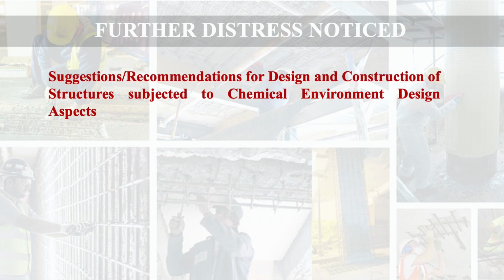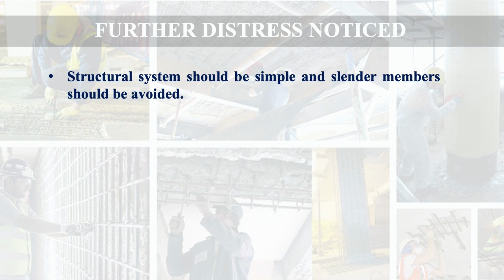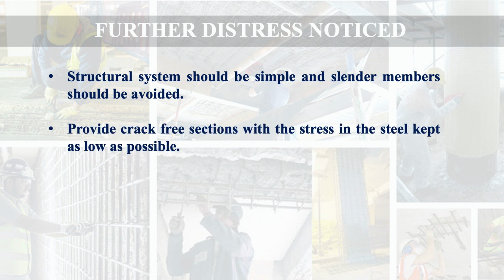Then, suggestions or recommendations for design and construction of structures subjected to chemical environment. What are the design aspects? The floors supporting the equipments shall be delinked from the main building, providing independent supports and foundation for the members of such floors. Then structural systems should be simple and slender members should be avoided. Provide crack-free sections with the stress in the steel kept as low as possible.